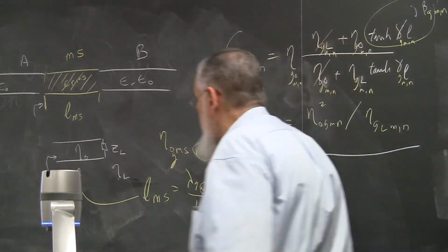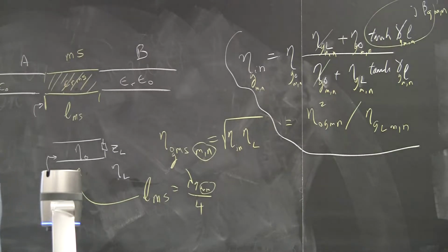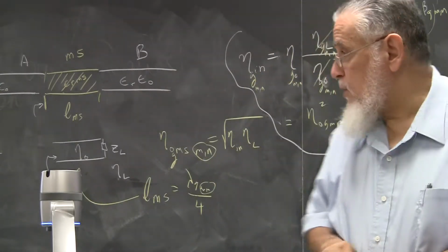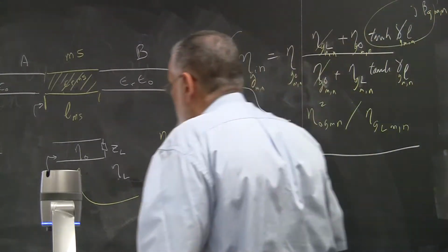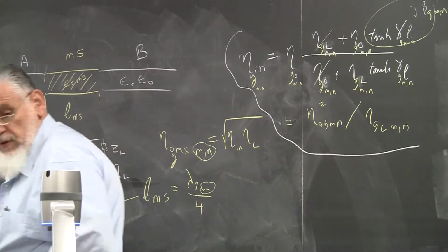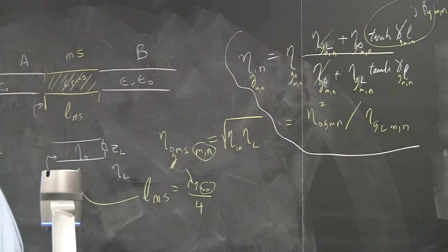So we'll look at the first section of the guide, guide A, and we find that the section operates between these two frequencies, FC1 and FC2, the first cutoff and the second cutoff. You look at the second guide, and it will have its own operating frequency. Let's do that in a different color, red.